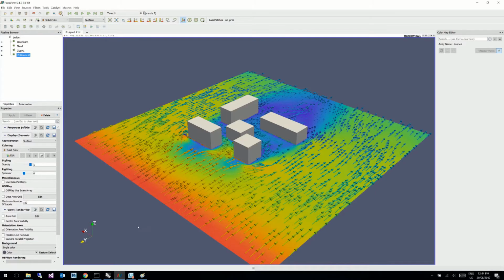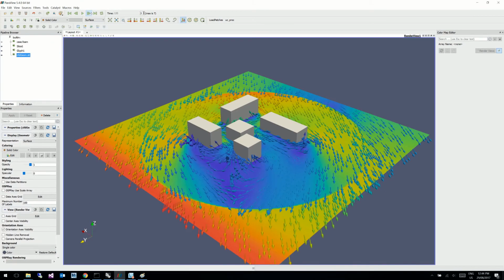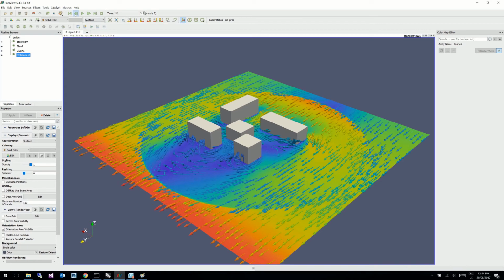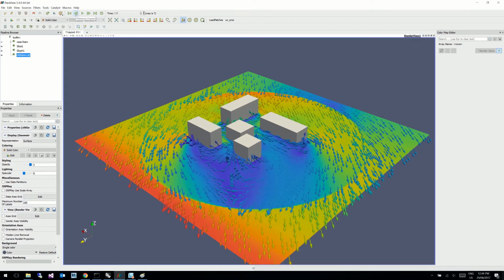Just so you know what the results look like, here is the results loaded up into Paraview, and you can see we've got a very simple domain, external CFD, fine, but you can see then we get multiple wind angles solved. And you can see the results are only valid for within the turntable. That's because of the way that we rotate the mesh and map the results back onto a single mesh. But doing this allows us to carry out some more sophisticated analyses, which is just not possible using multiple meshes and then mapping, or it could be very challenging.